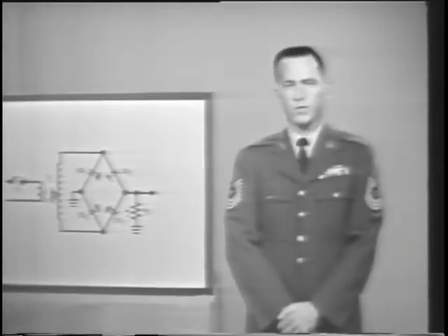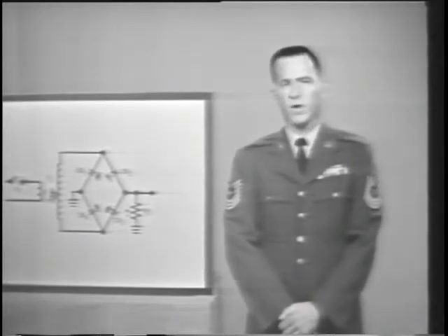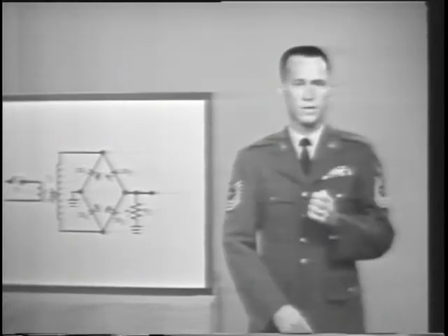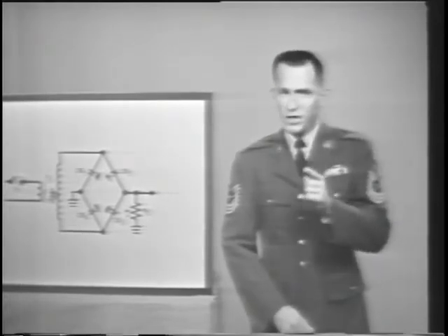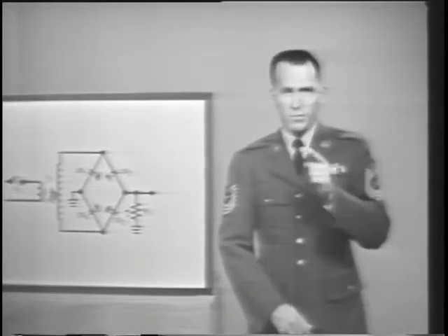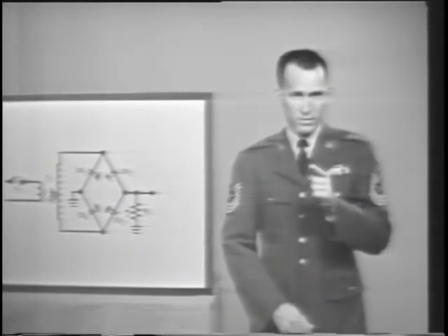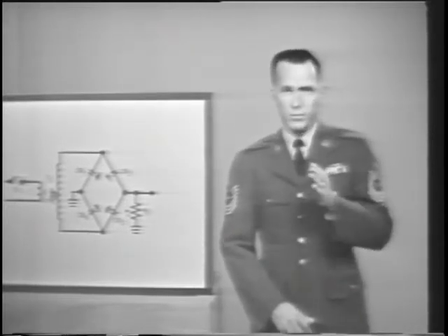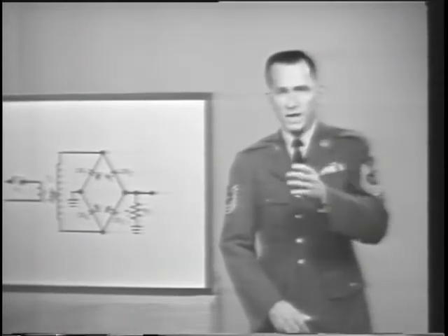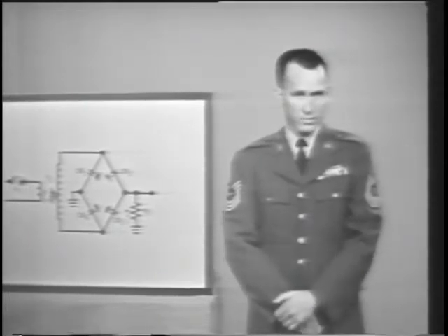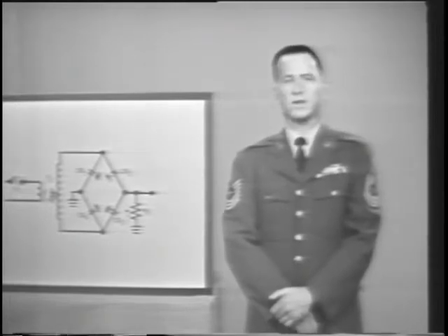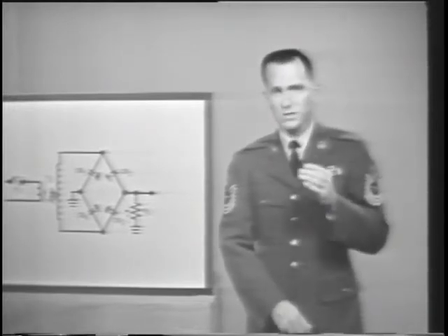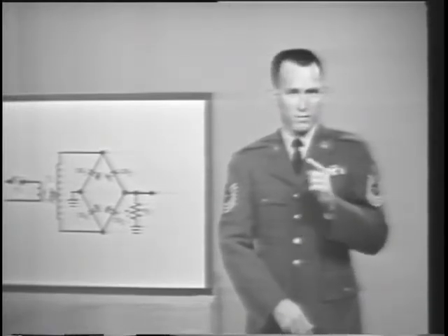The second point to remember is this. When converting from primary voltage to secondary voltage by multiplying with the step-up ratio, the secondary voltage only changes in amount. Now if the input is given in its effective value, then the secondary voltage will also be in its effective value. If the input is given in its peak value, then the secondary will be determined in its peak value. So the first thing to do in calculating any voltages in the circuit is to use the transformer ratio, if any is indicated, and then determine the secondary voltage.